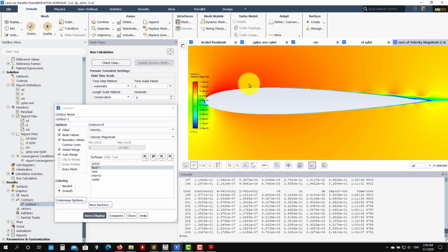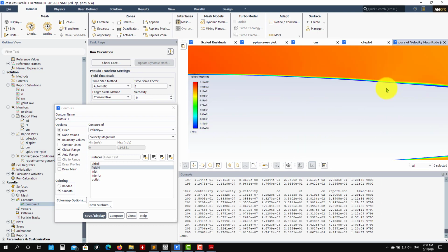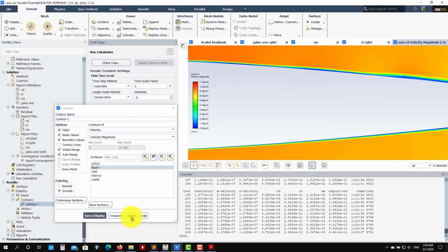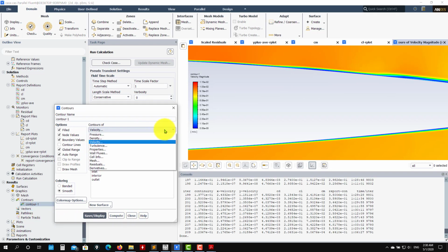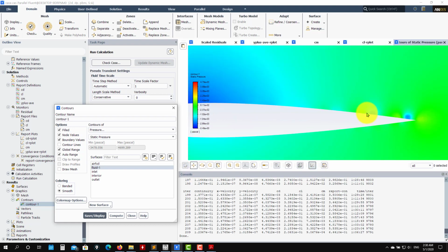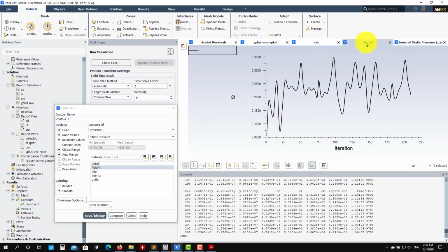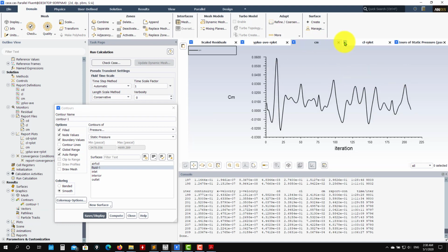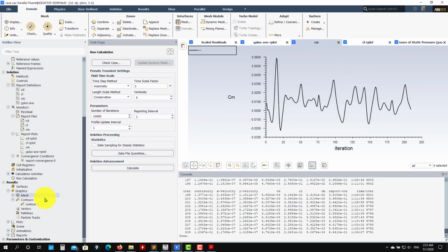In the case with the turbulence model, it was very stable, but here you see that you have some separation. We can also go to pressure, and probably we can see here that you have the shedding. You have some vortices that are being shed here, boom, boom, boom, and this is what is happening in this case. As you are resolving all the scales, you are not capturing the right physics because you are missing your unsteadiness. Now you are in a steady mode. Probably these quantities that you are averaging there are not very realistic.